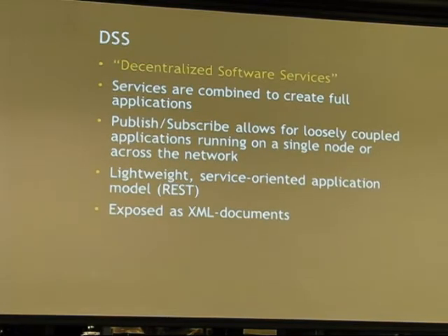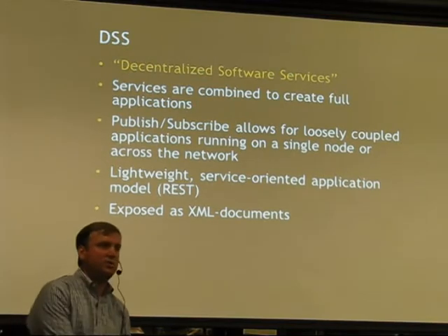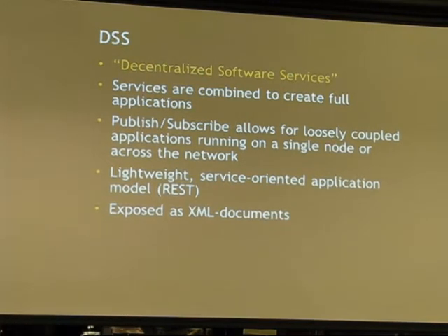Now I'm going to show you a little demo code in a minute that'll hopefully illustrate this better. So DSS is different. You're using CCR for writing all your little processing code and so forth. DSS is the larger infrastructure that's responsible for coordinating all these different services that you've written. So in the case of the robot, I create the tripod robot. I have a service that's handling the pan tilt mechanism. I have a service that's making sure that this thing is driving in the right way and so forth. And DSS's role is to make sure that the messages and so forth are getting passed back and forth to these different services.